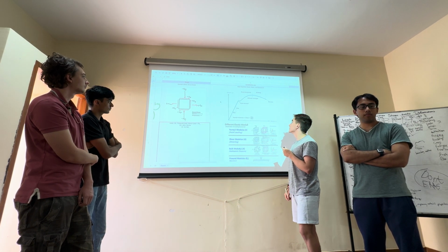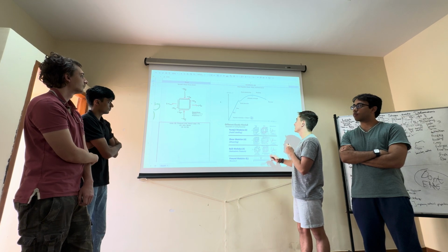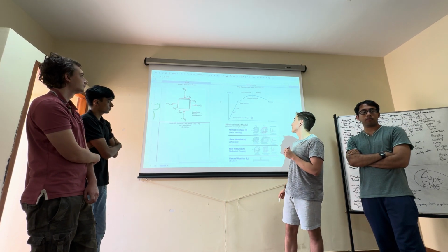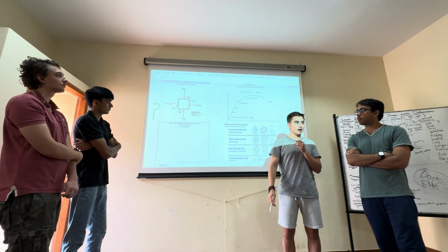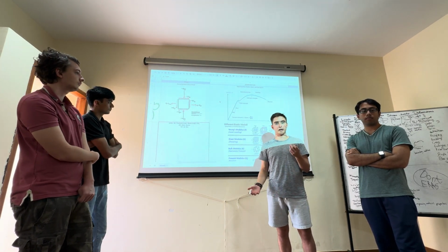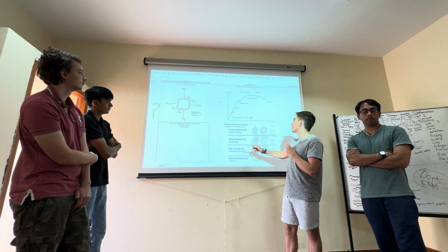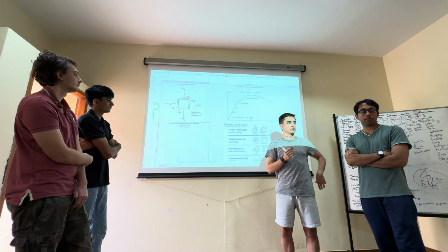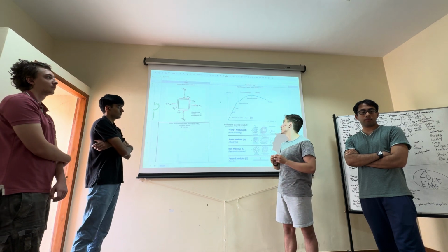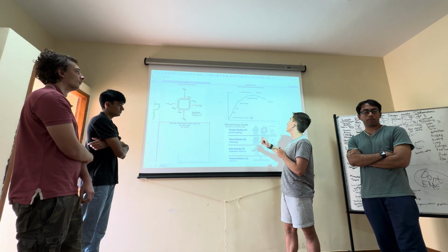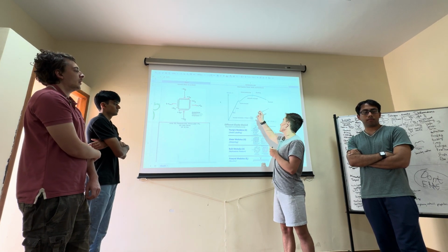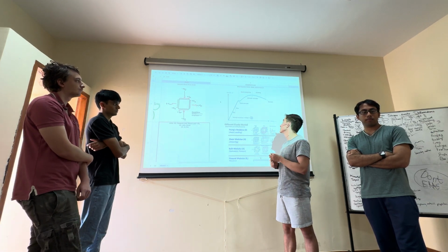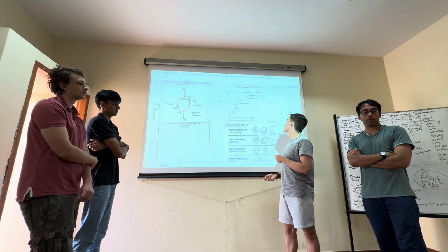And then for the constitutive law, we have the stereotypical graph of the stress versus the strain. This of course varies by material, but this is the generic graph, where you have the linear section, which allows you to define Young's modulus if you're doing an experimental test of a material whose Young's modulus you don't know. Then you get the strain hardening and the necking, which happens to different extents in different materials, or might not happen at all depending on the material.